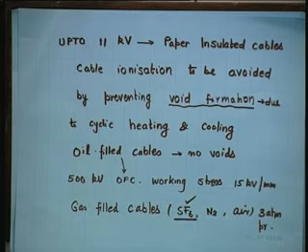So that is why you prefer oil filled cables, because then there will be no voids. 500 kV oil filled cables are used, with working stress of just 15 kV per millimeter. Gas filled cables are again very popular, especially SF6, nitrogen, air, at 3 atmospheric pressure. SF6 circuit breakers are also very important. Similarly, vacuum circuit breakers, we will talk about them also as we go ahead.